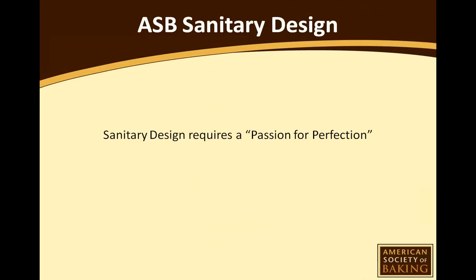Sanitary design requires a passion for perfection. FDA and USDA regulations require that equipment should be designed of such materials and workmanship as to be adequately cleaned and properly maintained. This requires that food processors and equipment suppliers understand not only what is to be cleaned, but also how it will be cleaned and under what conditions. Wet versus dry, type and amount of chemical, frequency, time frame are some of the questions to be considered.